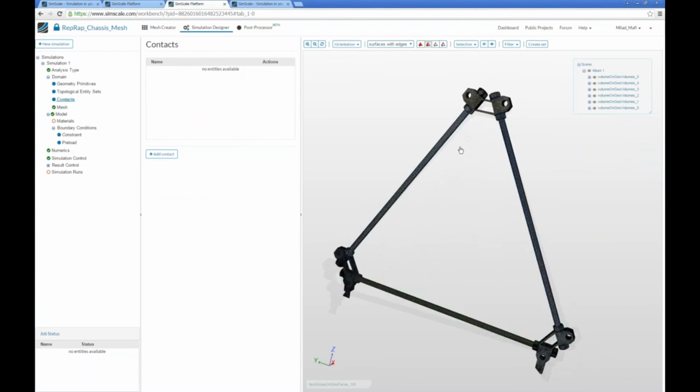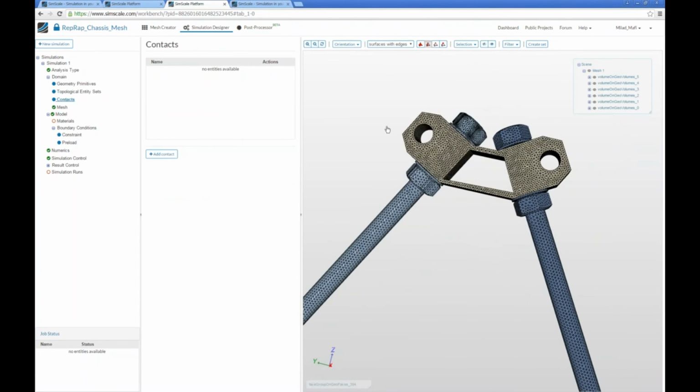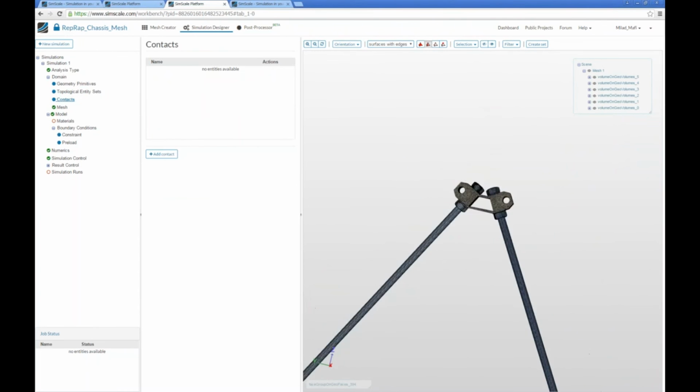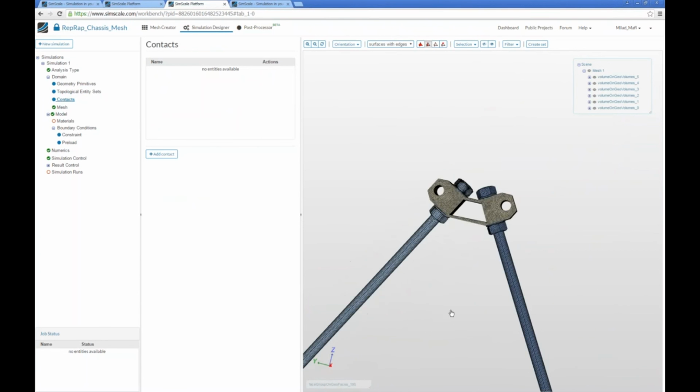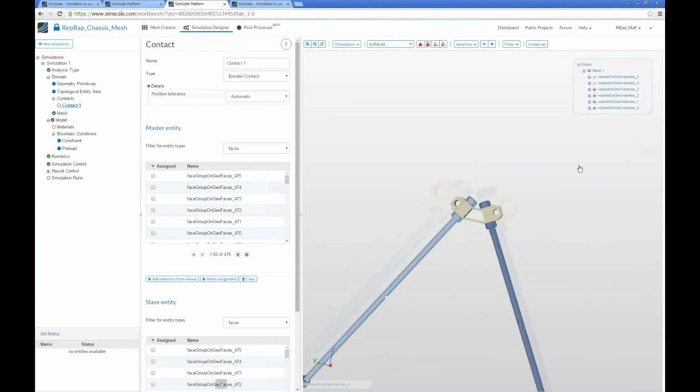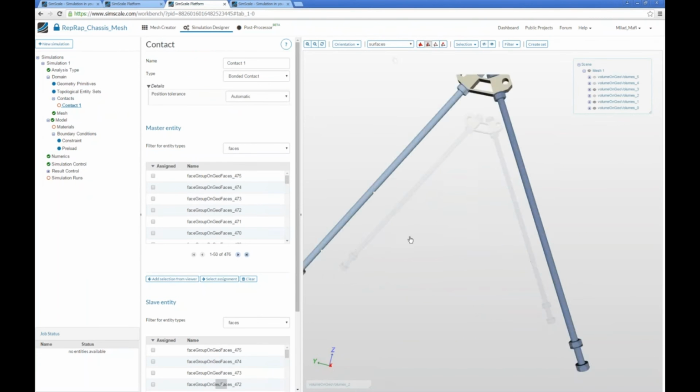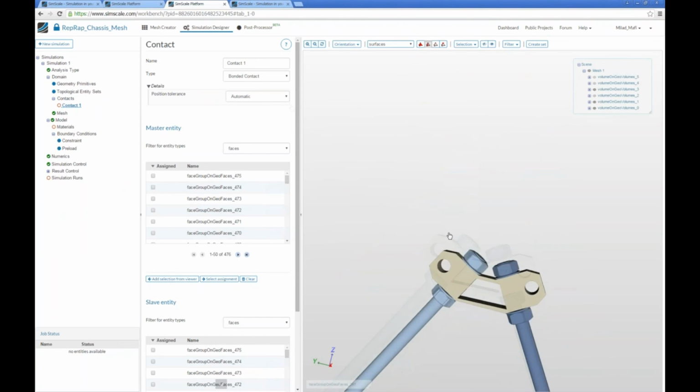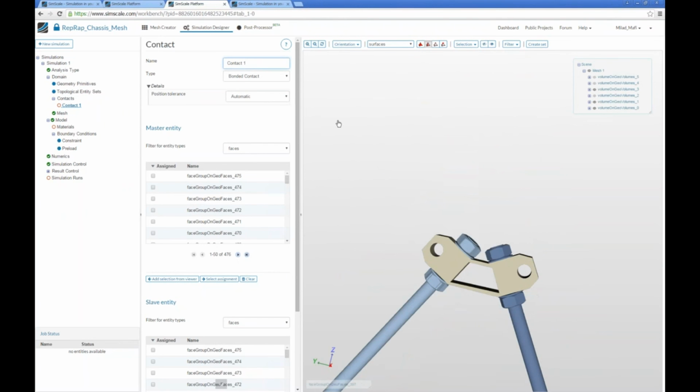And we will now just do 3 contacts, from around one of these plastic connectors, to show you how it works in principle. So let's start with adding a new contact, and we will now focus only on this connector. This is body 3, so we can turn off the other ones, and we can also turn off this one. Okay, and let's start with this contact. Let's call it contact 3 for body 3, and 0 for the number of the first contact. So we count 0, 1, 2.